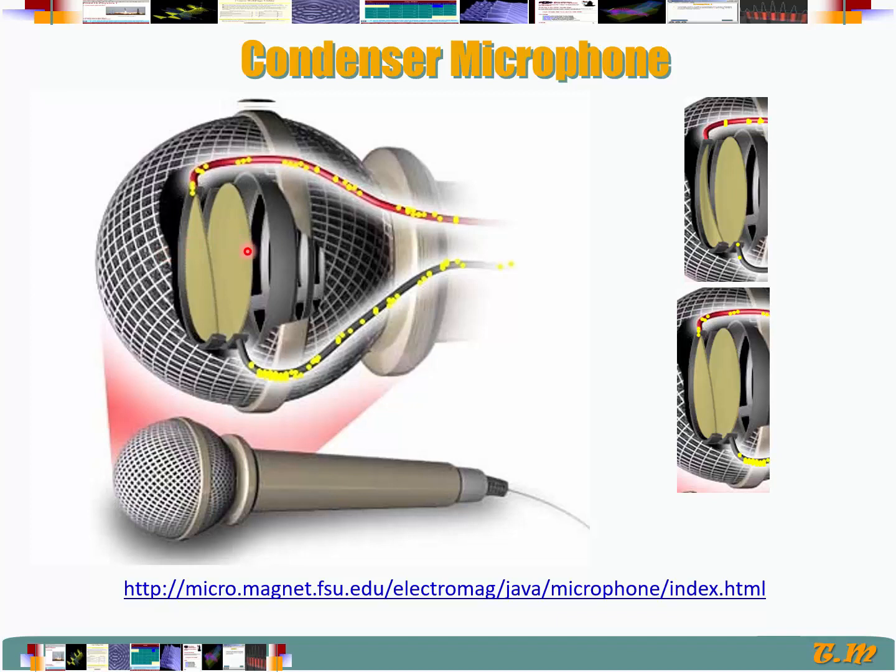Now, the pressure due to the voice is going to put these plates closer to each other or further apart. By putting them closer to each other or further apart, the capacitance of this particular parallel plate capacitor is going to change. And as it changes, that would affect the current in the electrical circuit.